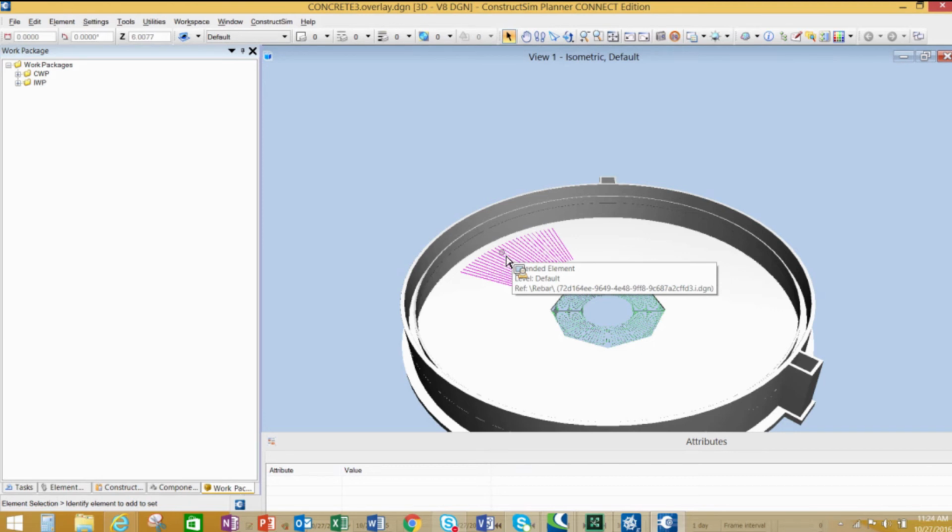For instance, a standalone foundation. I have found by being able to do that is we do not have to go back and buy additional rebar. And we have the ability to have the rebar formed and cut or rolled or bent off site prior to bringing that to site, so you end up can reduce your safety risk,